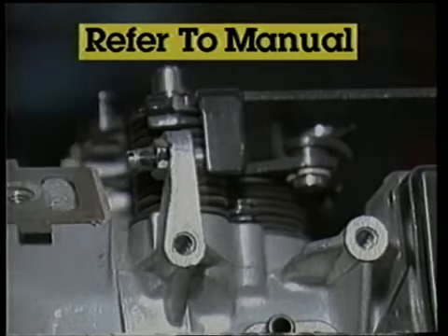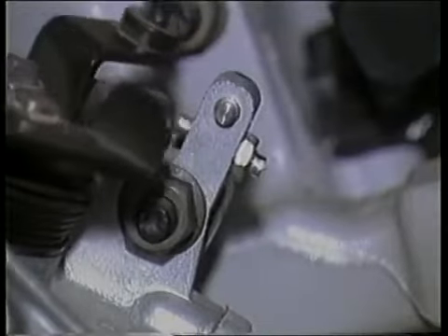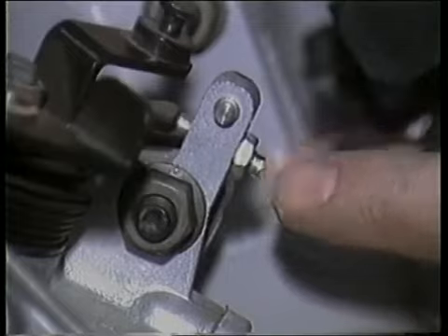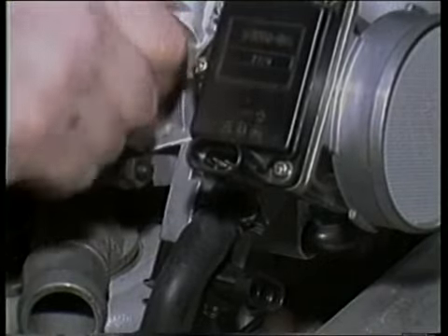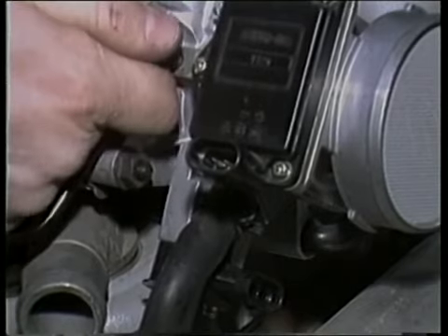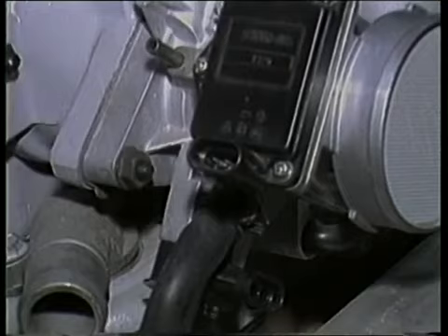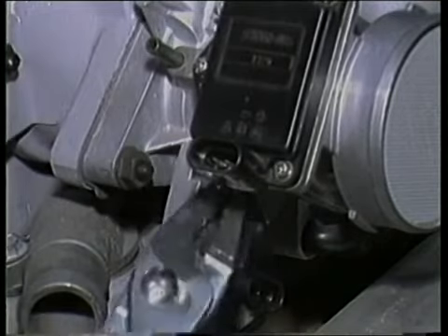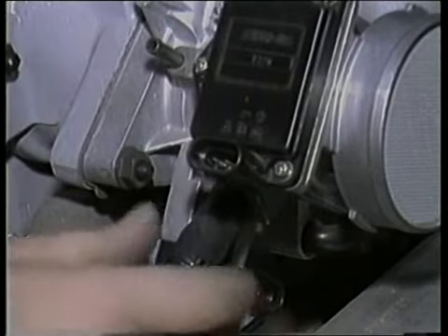When making throttle lever adjustments, remember to always refer to a factory service manual. If screw adjustments are needed, it is critical to use proper methods, since it can affect computer feedback from the throttle position sensor and output to the idle speed control solenoid or motor. To remove a throttle body, disconnect all wires, vacuum hoses, and tubes. Be very careful not to damage hoses and wiring.